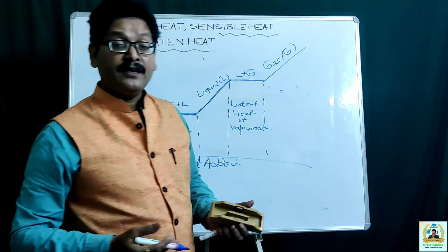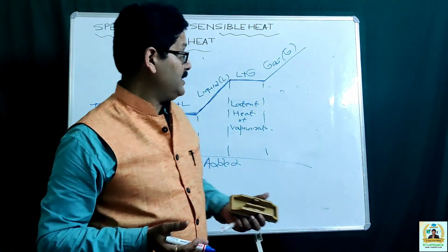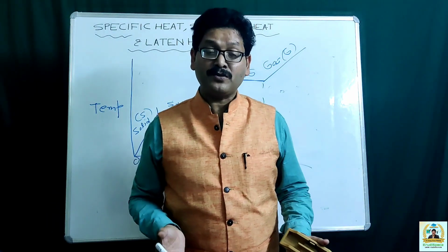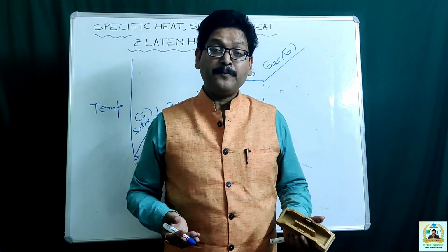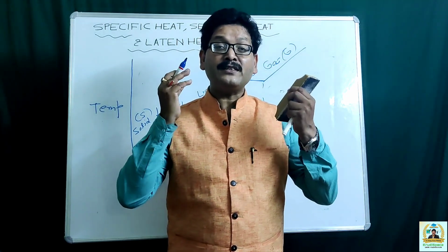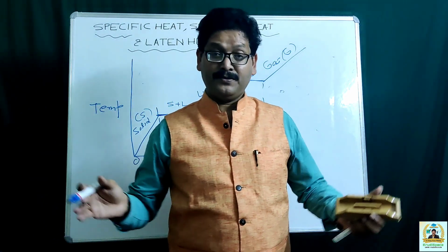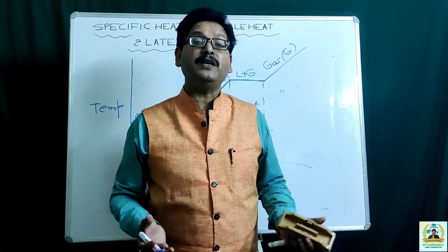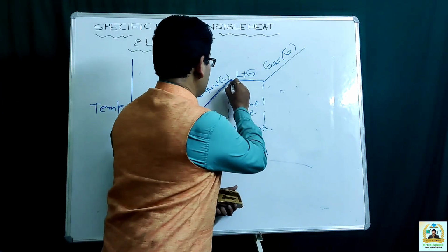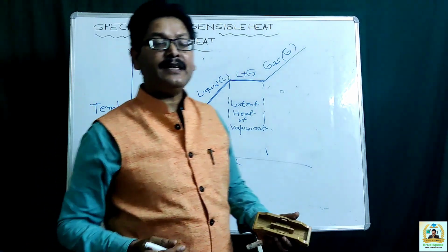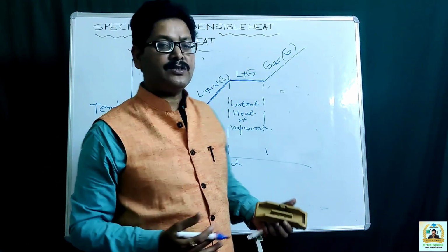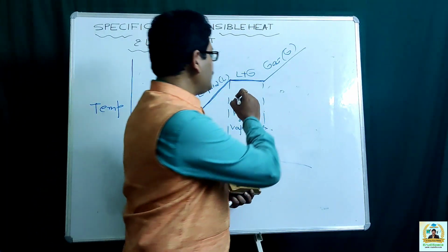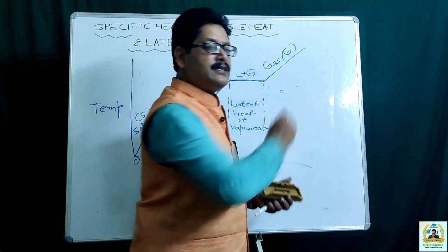Here again the heat energy is being utilized in overcoming the force of attraction existing between the liquid molecules. We know that in liquids, the molecules do interchange their position, but they cannot move apart. So, for that some amount of heat energy is to be supplied. So this is nothing but your latent heat of evaporation, and once the entire liquid is converted into gas on further heat addition, there will be a rise in temperature.